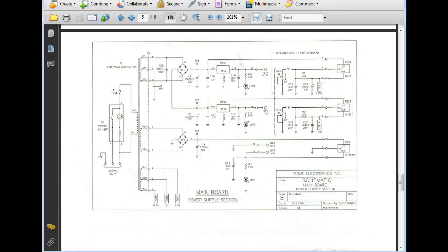So this is the 32 volt center tap transformer, giving us our plus and minus. This is rated at a quarter amp. This guy says it's 9 volts, and it says 1 amp. But I think the trainer says 5 amps. I have to look at that.